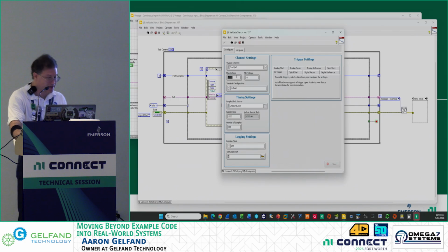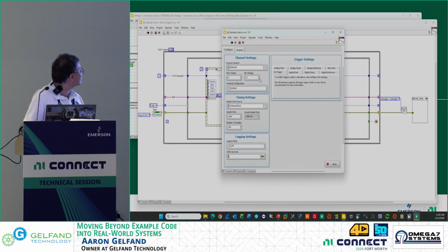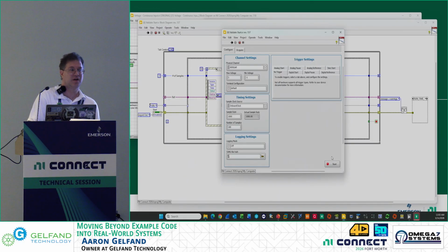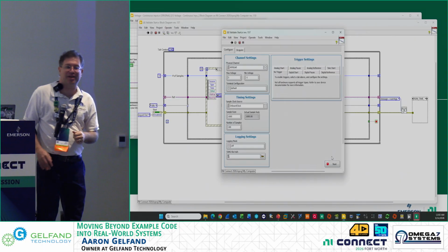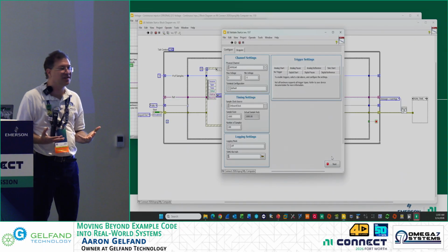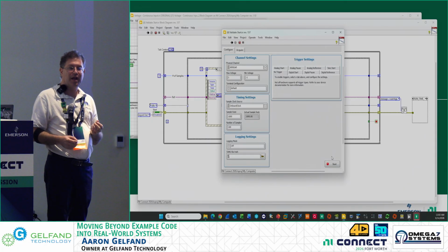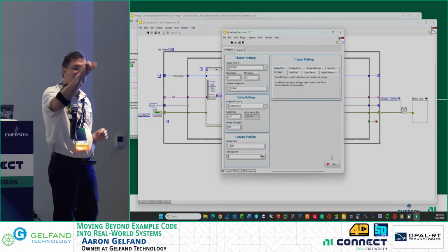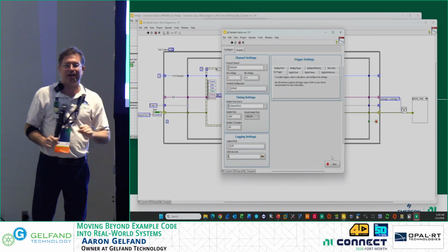So I can bring this back to 5 volts, click outside of this, and in this case, I'll also have to switch to the appropriate module, and now I've got a valid configuration. Now, ideally, you don't just want to have that stop button or start button disabled and not have any information to the user why. And so that's when we start doing things like little triangles with the exclamation in them next to the value that is illegal.